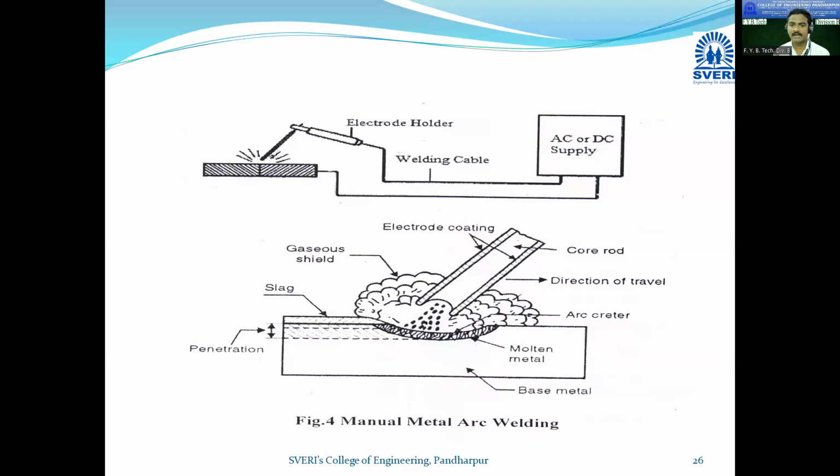So that is the advantage of keeping it in the atmosphere for solidification. Air acts as a coolant, so the welding will be very strong. When you keep it for solidification in atmospheric air, the strength will be good. But when you spray water, definitely the strength will be reduced. So that care should be taken while doing the arc welding process.